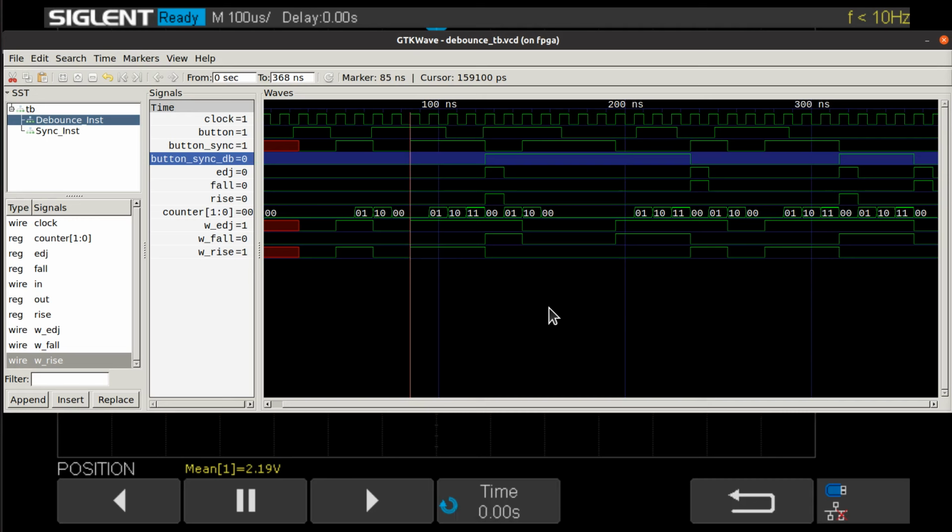In case it's lost on you, the value of that would be you could use a slower running clock to deal with your keyboard debouncing and not use tons of LUTs and all your counters over there, while you're using a high-speed clock to run the rest of your circuitry. All right? So that's a little bit more advanced topic, but you might run into it when you're poking around on the internet.